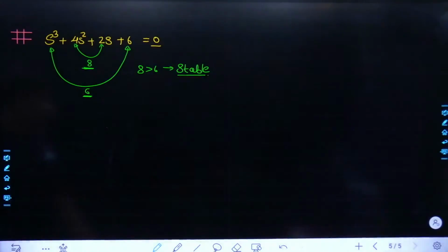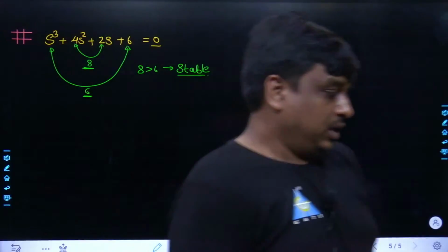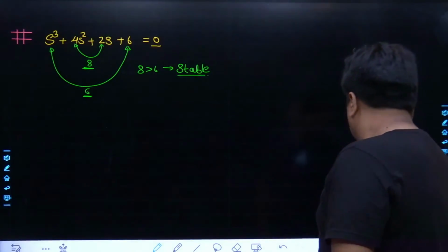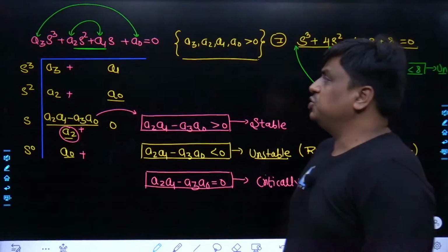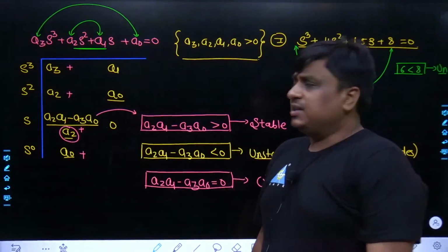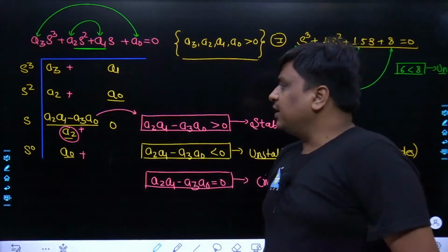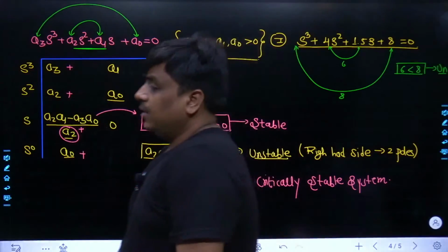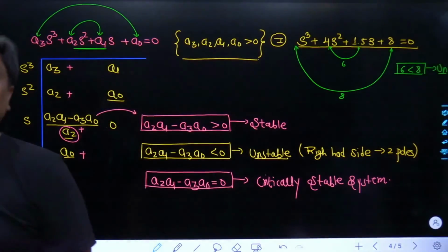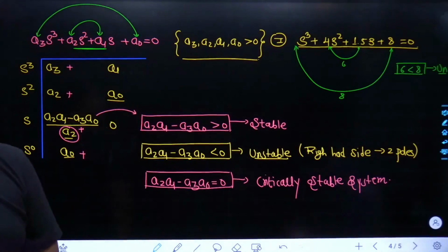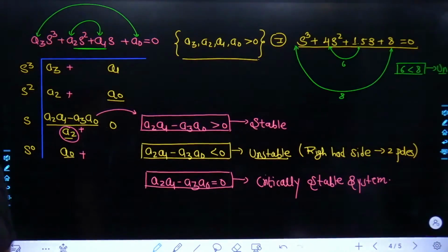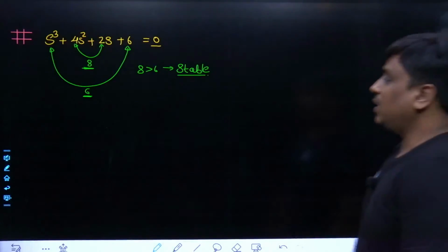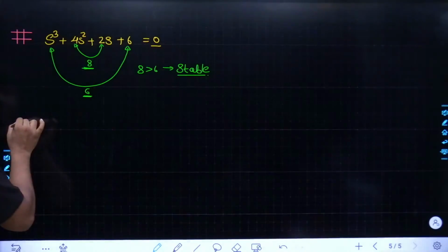Till this point, I don't think any student would have any kind of doubt now. So why am I revealing this short trick? Because most of the time you come across a characteristic equation which is cubic in nature. So rather than going to the complete analysis over the Routh-Hurwitz table, you could take this alternate. Could you really understand what exactly I have been talking about? Yes, no? Now let me take the last, but never the least.